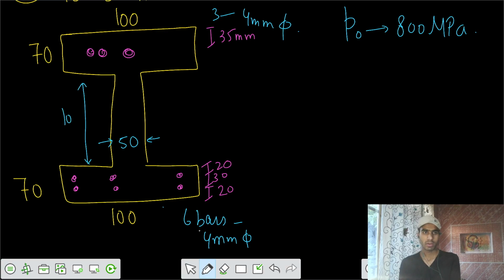and the depth of the web is 100 millimeters. If this is symmetric, and we are going to ignore the equivalent cross section, I would say the neutral axis is at the mid depth. So the neutral axis is at the centroid. This is our neutral axis.